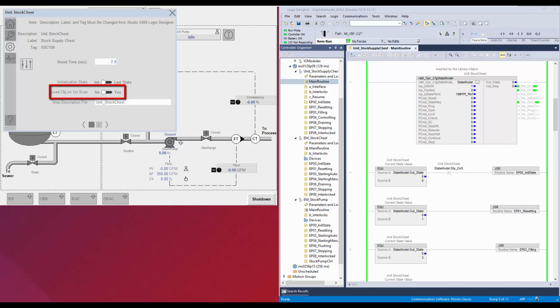This parameter is set when configuration changes are done in program mode of the controller or in the offline ACD file. When set as yes, the state model instruction will copy the configuration from configuration parameters on first scan. The action is only done once and the parameter is reverted to no after copying.